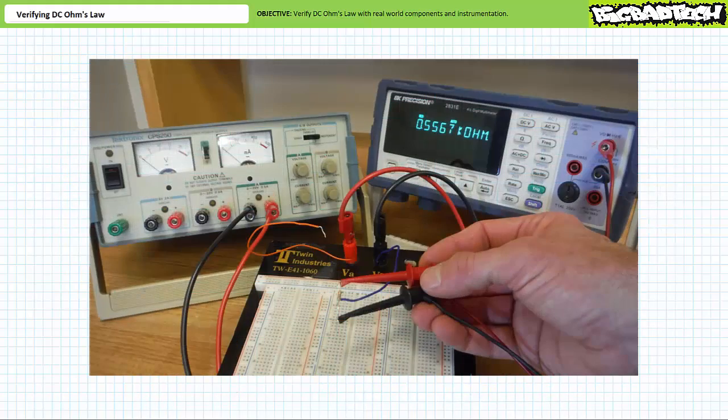The 4-band resistor color code for a nominal 560 ohm resistor is green, blue, brown, gold, meaning 5, 6, followed by 1, 0. Given a plus or minus 5% tolerance, we might expect this resistor to be between a low of 532 ohms and a high of 588 ohms. An ohm meter measuring the resistance of a resistor matching this description demonstrates it has a resistance of 556.7 ohms, well inside the expected tolerance range. This being said, given this resistor has a slightly smaller resistance than its nominal value, we might understandably expect our observed current to be slightly higher than our theoretical calculations might suggest.